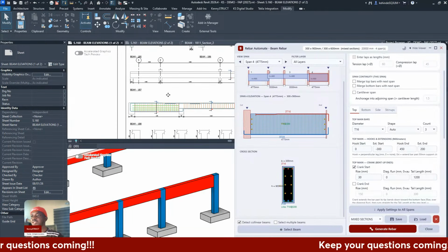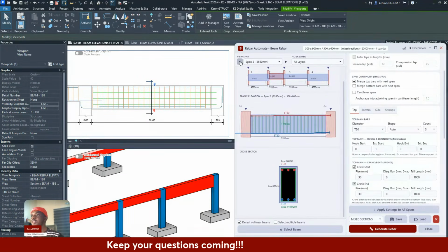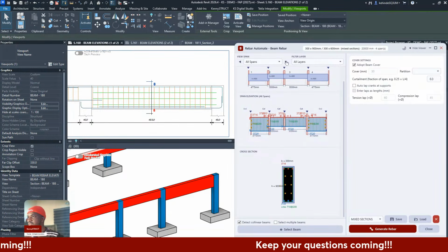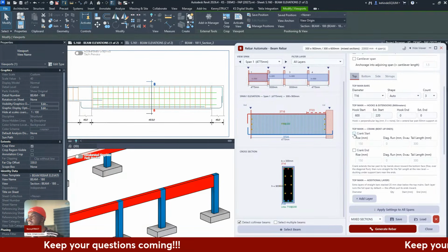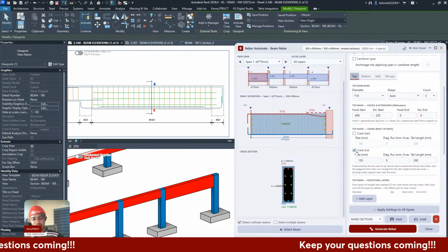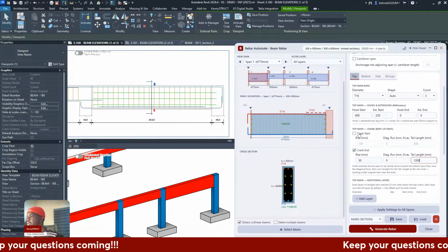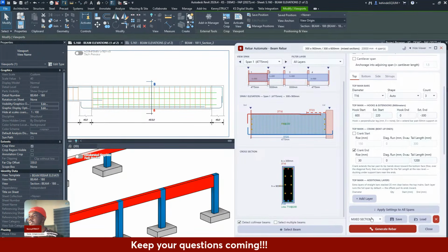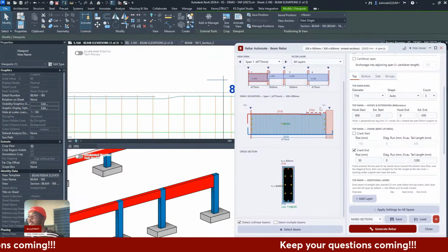Aha. And do this. And then replicate this thing on the same span, the last span. I think that's span 1. It's going to be at the end, I believe. Span end. I keep this as 30, 600, or as 1,200. And the extension at the end is going to be -300. Let's see how it looks. Amazing. As you can see, you can even tell from the viewer what to expect.